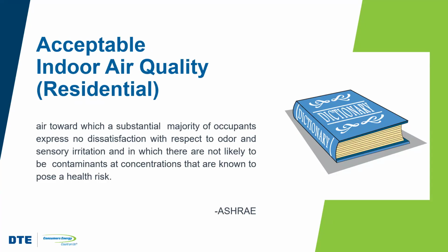Now, on the commercial side of things, we define acceptable indoor air quality specifically as air in which there are no known contaminants at harmful concentrations, and with which the substantial majority of occupants, defined as 80% or more, would not express dissatisfaction. For the residential market, we kind of pull that back a little bit.